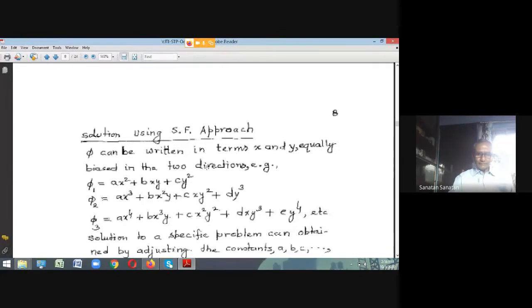So it is actually some stress condition. Similarly, minus ∂²phi/∂x∂y will become minus b. So this stress function indicates some stress state in a body, given by the values of the constants in this second order polynomial in x and y.